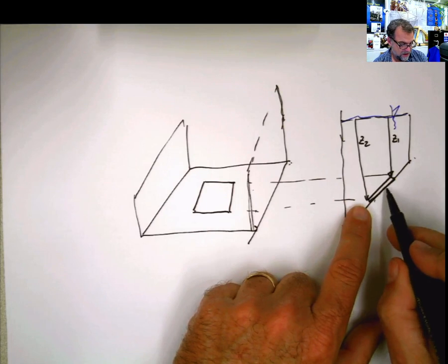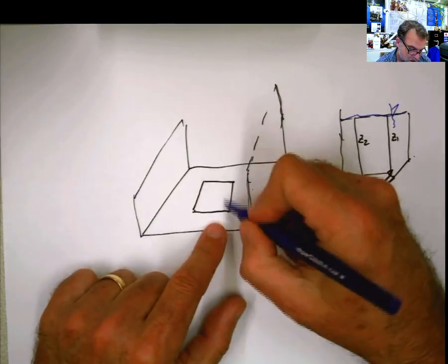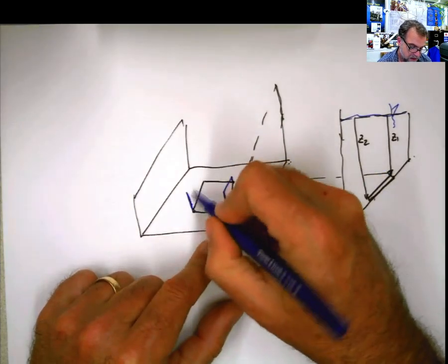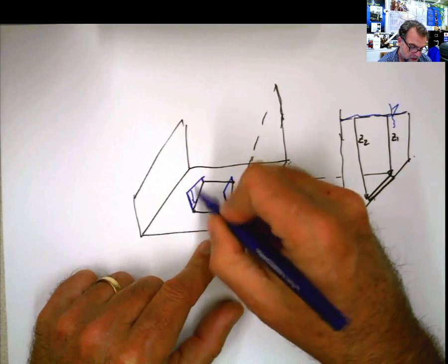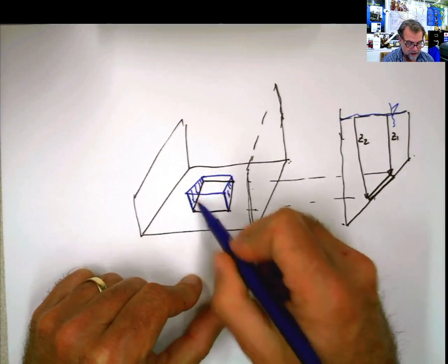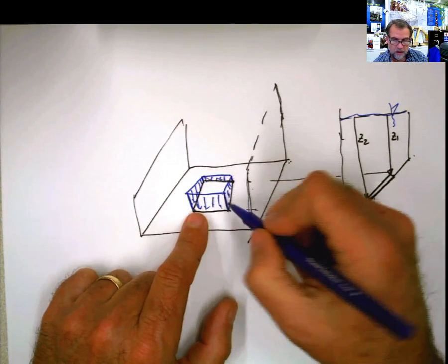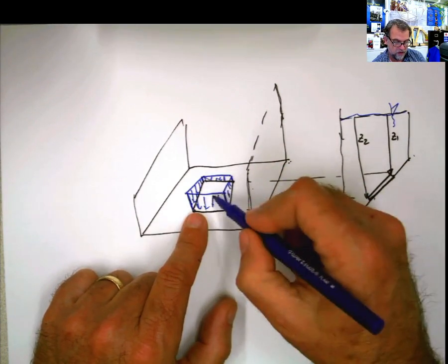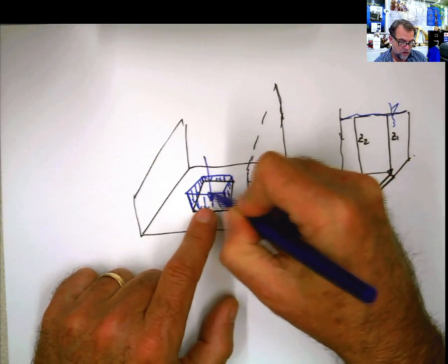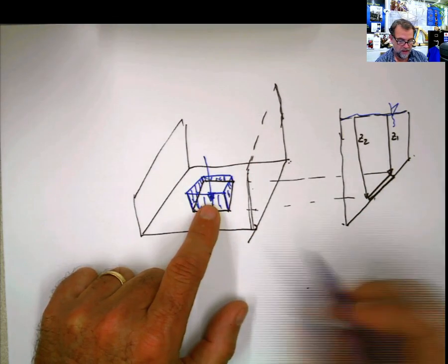That means that this plate is going to be subject to two different pressures. If you look at the volume here, the pressure is going to be bigger in this part and smaller in this part, because it's changing like that, and that's going to be a volume of pressure. But the principle is the same. What is going to be the resultant force? The resultant force is going to be the resultant from that volume, and what is going to be the location? The location is going to be the centroid of that volume also, or the center of pressure, which is called that in this case of that volume.